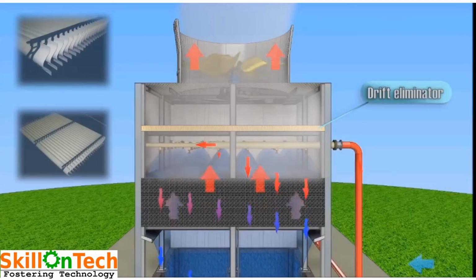One more important thing which is to be taken care of is the gearbox. The oil of the gearbox shall be maintained properly and it is to be topped up from time to time. The vibration of rotating components should not be more than 4 mm per second for excellent performance of rotating components.